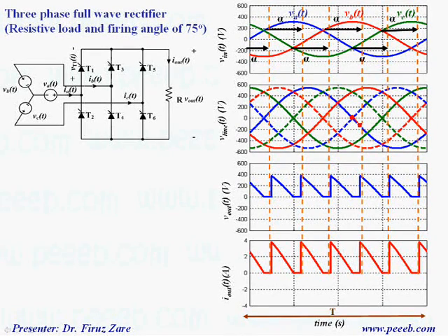So from this time till this time, over this period, because the line voltage appears across the load, the output voltage is getting negative. Because current is voltage divided by resistance, and the voltage is negative, the current should be negative. If the current is negative, that means the current through the thyristor should be negative. So in this case, the thyristor is getting turned off.